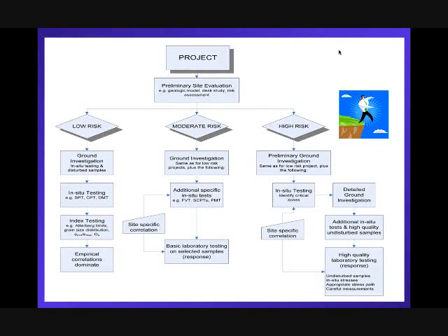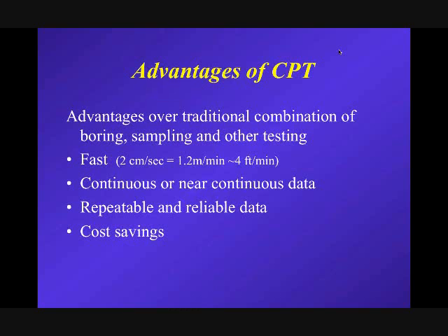But since the lab testing is slow and expensive, often the results of that lab testing are linked back to the in-situ testing so that the results can be extrapolated across the site. So CPT clearly plays a role all the way from low risk to high risk projects.